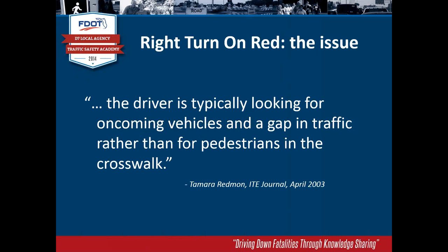So you've got this right turn versus pedestrian issue, same as the left turn versus pedestrian issue that I showed. And again, the driver is looking typically to his left to make that right turn on red, and he doesn't even see the pedestrians off to his right that might be looking to cross the road. So right turn on red can be a real safety issue if you do have large volumes of pedestrians, something you may need to think about.